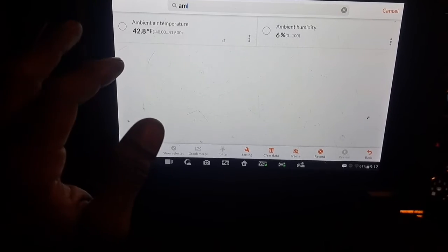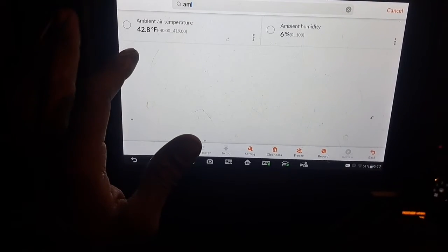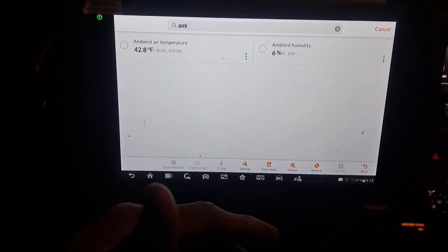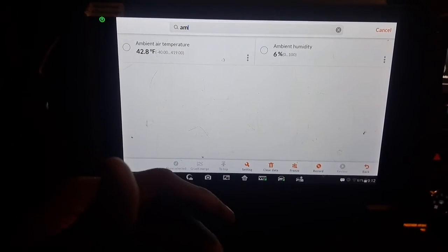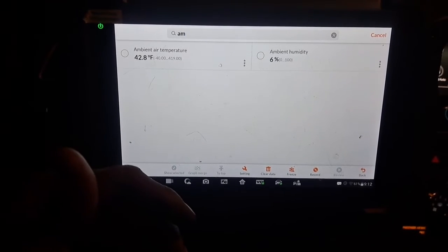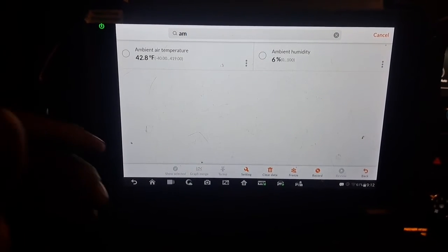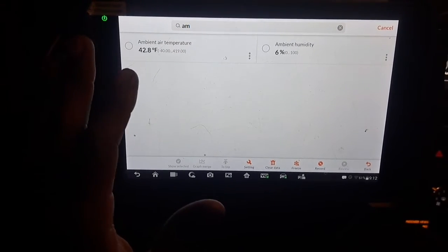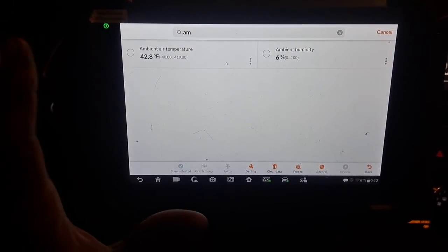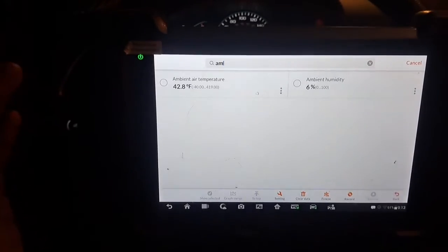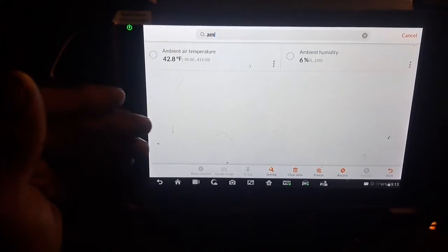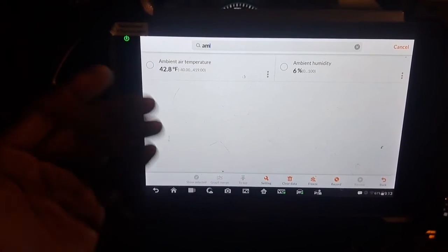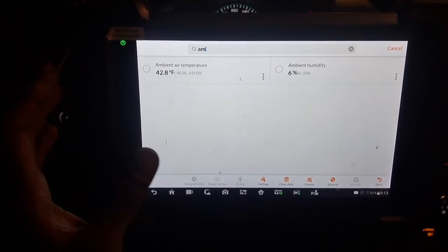Because if there was some problem, then disconnecting the circuit wouldn't have had both extremes, short to ground or open to positive. So I'm not going to question that. I'm going to hope that it's going to recalibrate on its own eventually. This is my first time having to deal with a recalibration for a temperature sensor. I'm going to assume that the dealer gave me the correct part.